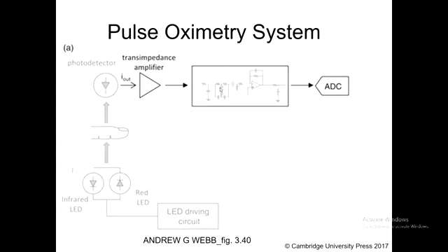That resistor and this capacitor? Who thinks high pass? Who thinks low pass? Good. And these two together? Okay, so can you get the feeling that this might be a bandpass filter or a notch filter, depending on the relative values? Either it'll let a select frequency through, or it'll stop a selected frequency, one or the other.